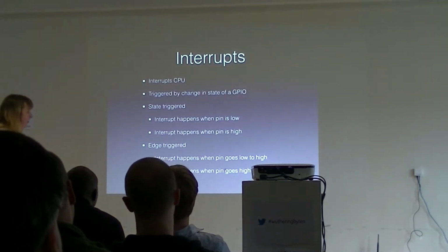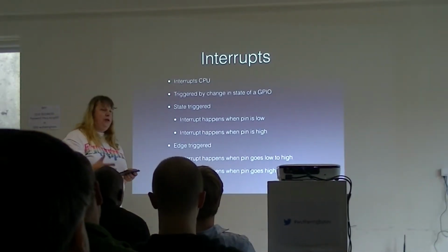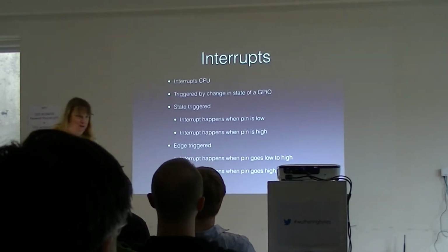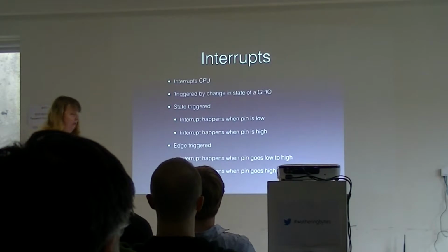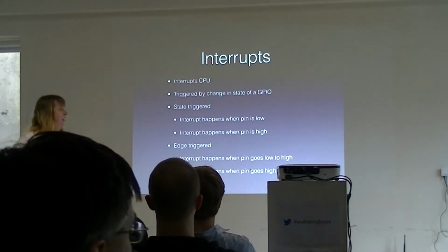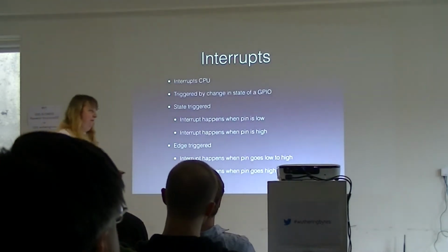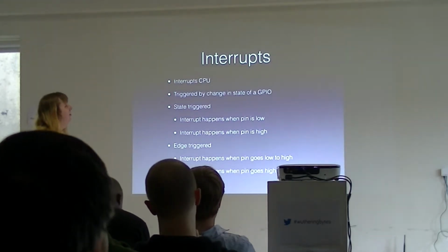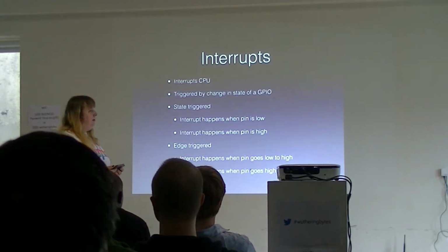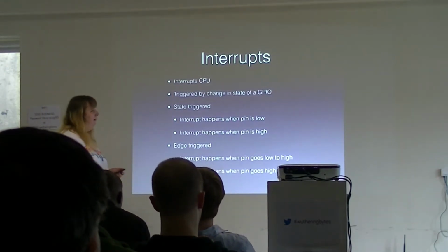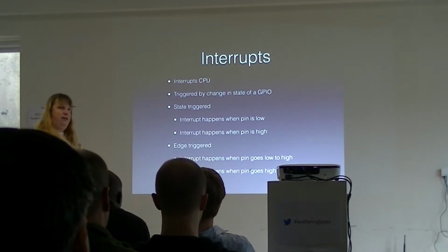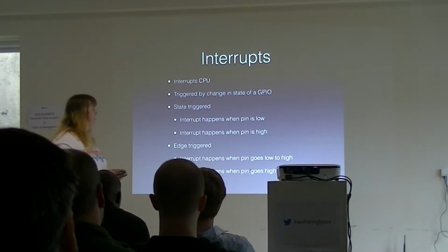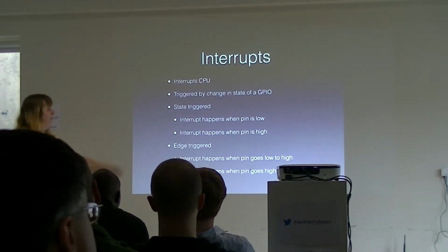Interrupts. Well, you can write some code that keeps looking at all the pins we're interested in, keeps going around in a loop, saying if something happened on that, something happened on that, something happened on that. Not very useful, uses lots of power, uses all your CPU, don't want to do it. What you can do is turn on the interrupts, which basically means if there's a change in the state of the pin, you go to the process and say I want you to do something. So that's what an interrupt is.